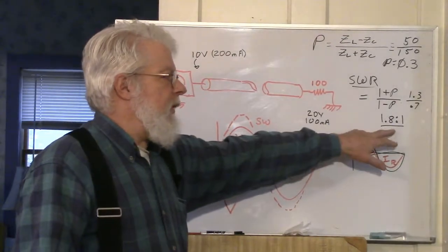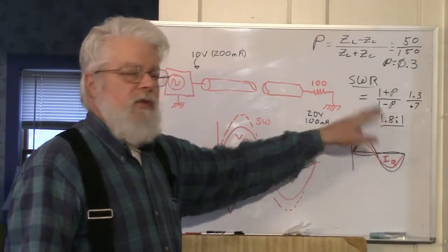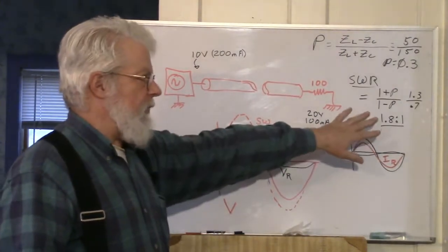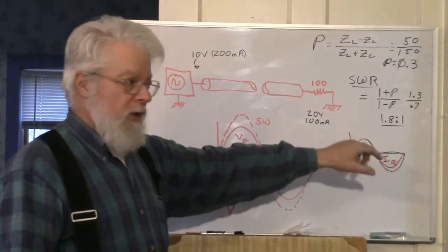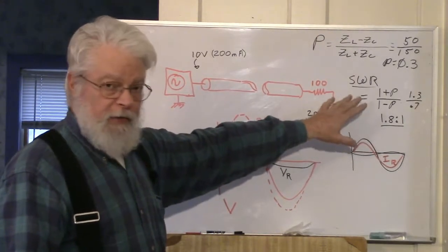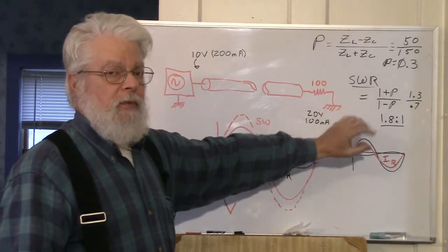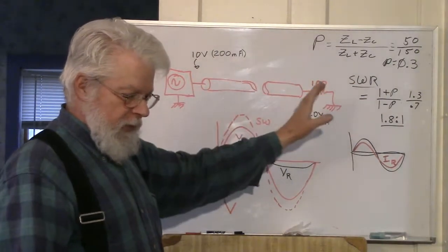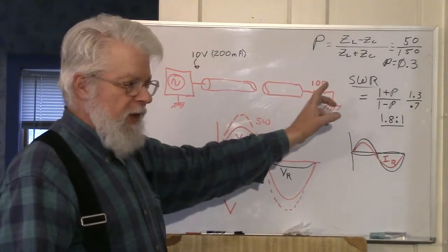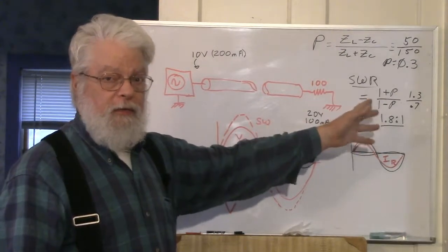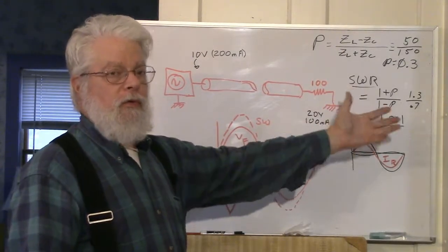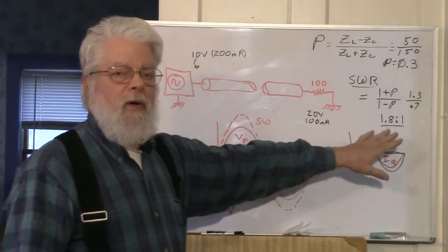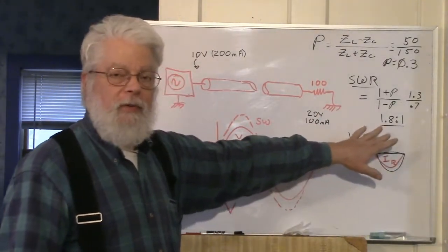Second important point is the SWR is not the ratio of the impedances. And this issue gets even more complex when you get into phase shifts due to reactance. When you have inductance and capacitance in your load such that the voltages and currents are phase shifted, and those shifts are reflected back, it gets much more complicated as far as what the actual standing wave ratio is.